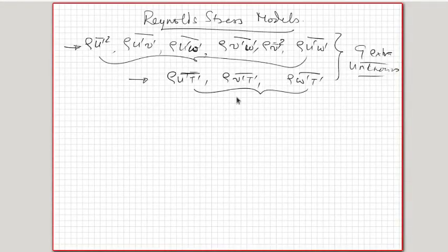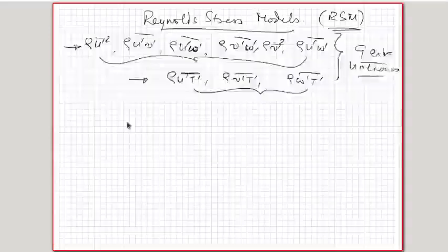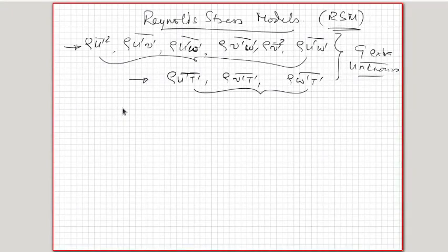Okay, so you don't use the eddy viscosity model or eddy diffusivity model, but you solve for these separately. So you will need to derive equations for each one of these quantities. Okay, and then you solve those equations. So they are called the Reynolds stress models or the RSM. So these capture the non-isotropic nature of the flow more accurately, but then the effort involved is a lot more. Okay, but there is a whole class of models that have been developed using this, and people do use these models, but these models are not as popular as the eddy viscosity models. So the other class of this is the eddy viscosity models.